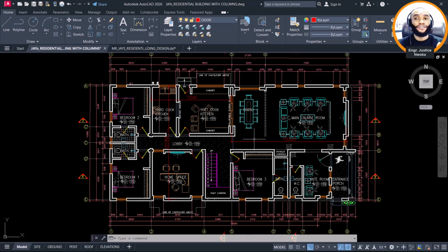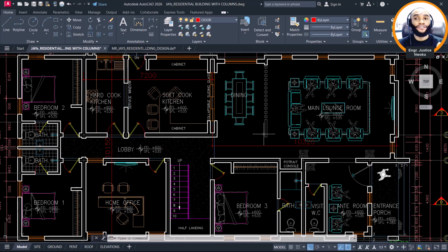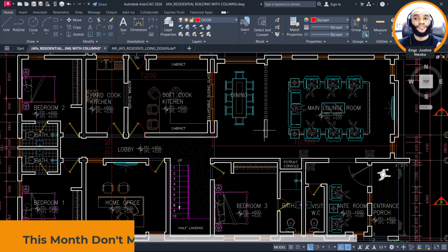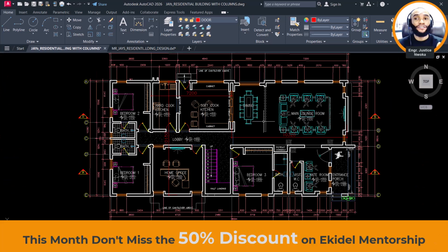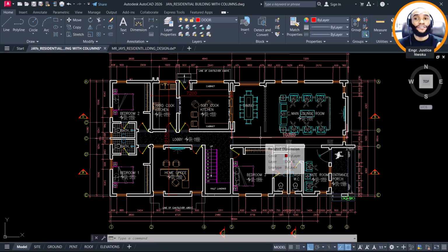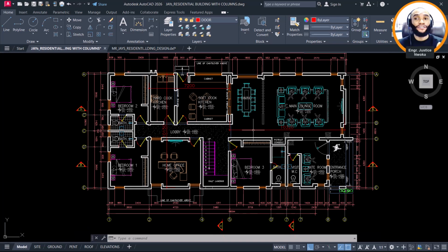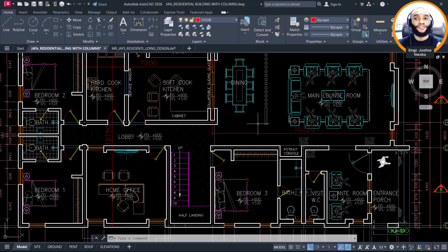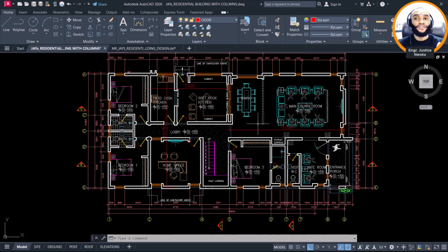Now, once you get your building plan like this, as a structural engineer, the first thing to do is to study the building plan and look at the features contained on it, because that will help you plan the structural framing, knowing that it is the framing of the structure that actually carries the structure. It is at that time you have to consider the size of the columns you are going to use, the column positions, how you want to panel the structure, and how you want your beams placed. All these things come at the stage of the structural framing.